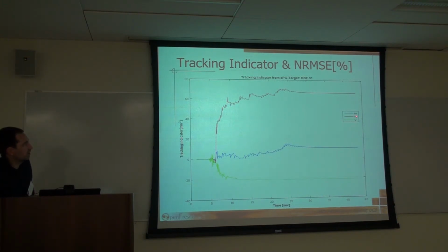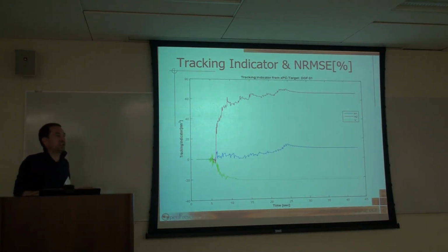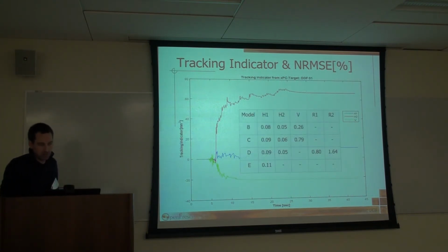And then degree of freedom 2 has a little more, so that's actually helping us. Like we learned yesterday, it actually introduces a little bit of energy dissipation into the system. But then in the vertical degree of freedom we had a little bit of lag, so there we're actually putting extra energy into the system, so negative damping. So that one can hurt us, but it stayed stable.